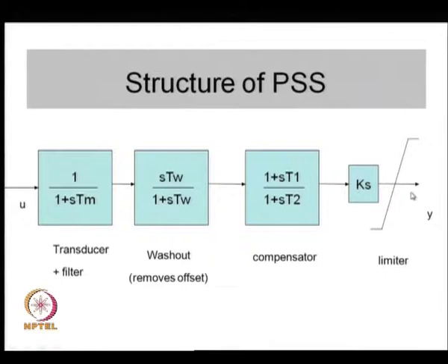Okay. So, these are the basic components of a power system stabilizer. These are in fact necessary, so that the output of the PSS modulates the controllable element appropriately, so that you get damping. You know, if you take a control signal, you can't just feed the control system with a gain. This may be possible under some very special situations, but normally you need to have an offset removal block as well as a compensator block. You may have one or more stages of this compensator. This is just one shown here. You may have to have a gain and then modulate the controllable element.